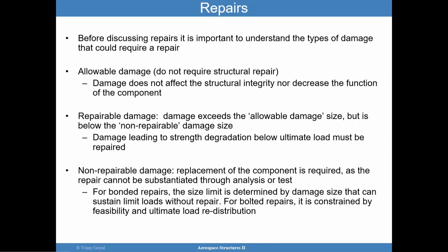For bonded repairs, the size limit is really determined by the damage size that can sustain limit loads without repair. And for bolted repairs, it is constrained by how feasible you can implement such a repair. But again, three types of damage, some of them not repairable, some of them repairable, and some of them don't require any repairs. So something to consider there.